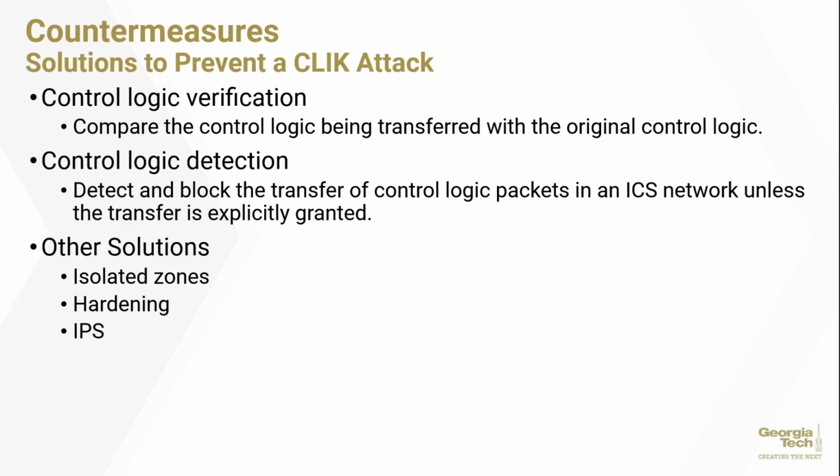Isolated zones could prevent things like zero-day attacks, because zero-day vulnerabilities are obviously not known by vendors or users, and by isolating old legacy PLCs, these zero-day vulnerabilities are less likely to be exploited, especially remotely. Hardening: when zero-day vulnerabilities like the one in this implementation are discovered and patches are released, those patches need to be applied to these devices, which will harden them against possible attacks. And finally there is an IPS, which can prevent any intrusion, very similar to the control logic detection mentioned before.